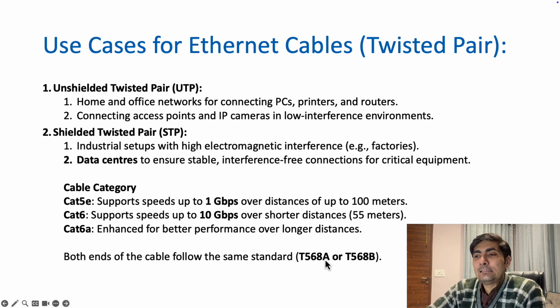And then there are standards T568A and B. I told you that there are 8 thin wires, and these are colored. 4 will have dual colors, like white orange, white brown, white green.